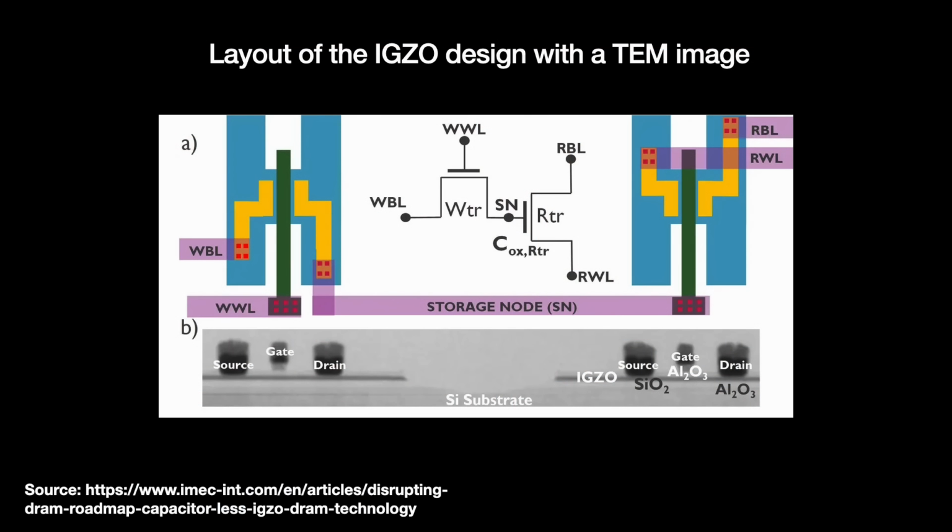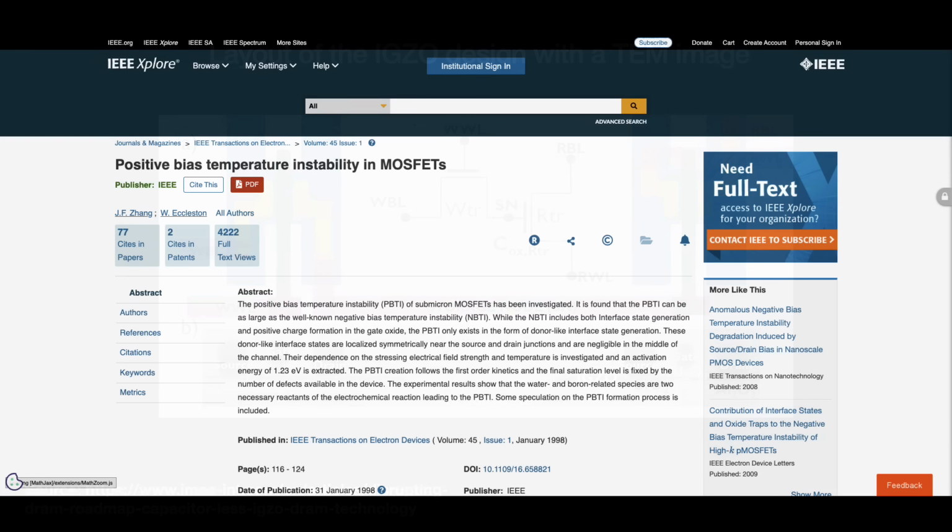Another is reliability. Traditional DRAM cells can work for many millions of cycles, but the 2T0C's capacitor, the gate, is small and fragile. It is susceptible to manufacturing defects and outside effects that can cause the transistor's performance to shift over time. One serious issue is called positive bias temperature instability, or PBTI, when a constant electric field at elevated temperature traps electrons in or near the transistor's gate oxide.